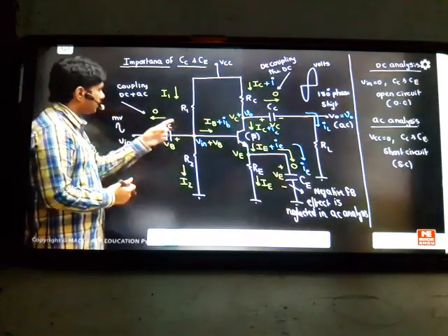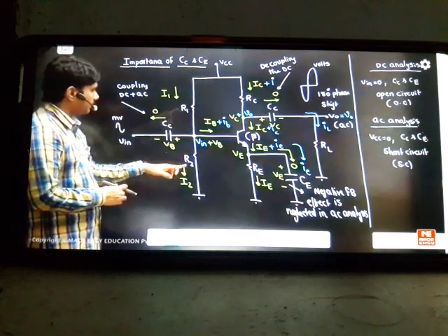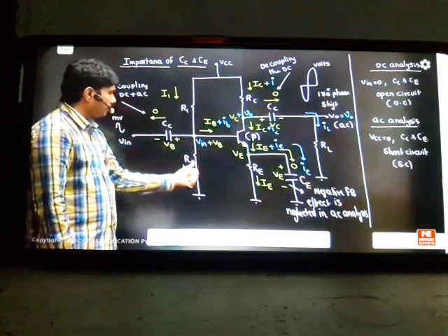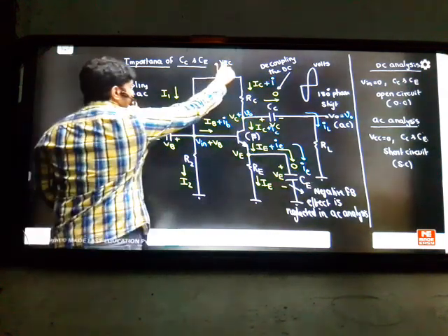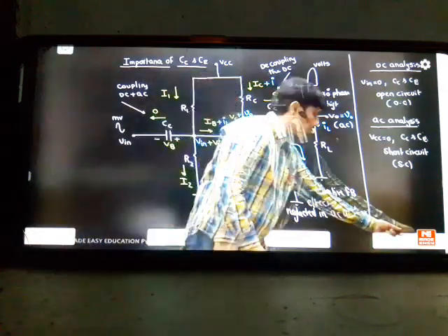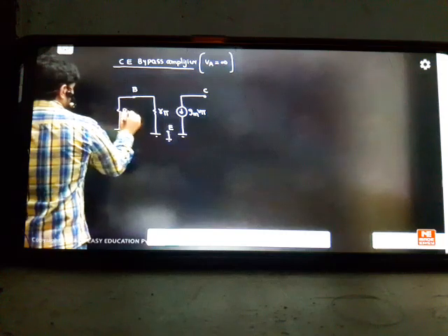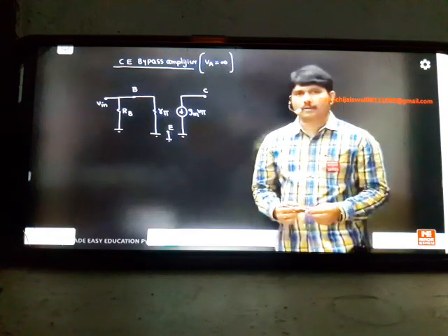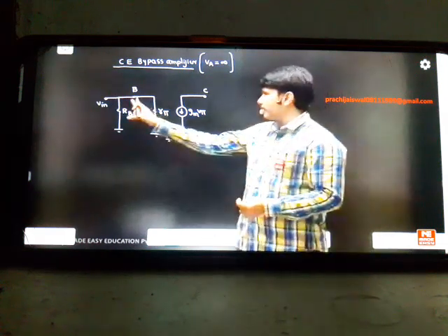After that, we have these two resistors, where VCC is ground for AC analysis. That's why these two resistors, with this being ground, we can take in parallel, R1 parallel to R2, which is RP. This R1 will bend like this because this is ground in AC analysis. In AC, this is ground, so R1 comes parallel to R2, and this becomes a short circuit, and this will be the signal. So here we have some RP, and here we have the signal. Throughout the classes, this is the story at the input. You will get some RP falling to the ground, because your VCC supply is ground here. That RP is nothing but R1 parallel to R2. After that, the coupling capacitor will be shorted and the signal will be there.